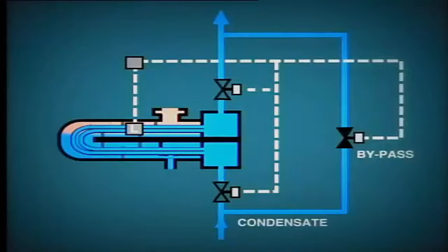In some installations, the high water level causes the condensate to bypass the heater altogether by automatically operating the motor-actuated isolating valves in the following sequence: open bypass valve and then close inlet and outlet valves. The matching of extraction steam flow to the heater and condensate flow through the heater takes care of itself automatically. As more condensate is pumped through the heater, more steam is condensed, so reducing pressure and pulling more steam from the turbine. In operating closed feedwater heaters, the operator must be sure to check that venting and drainage of the heater is functioning correctly.